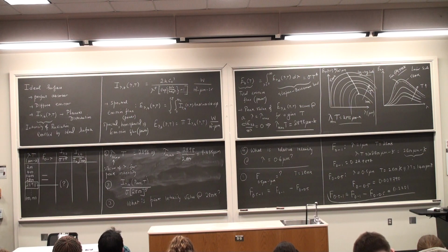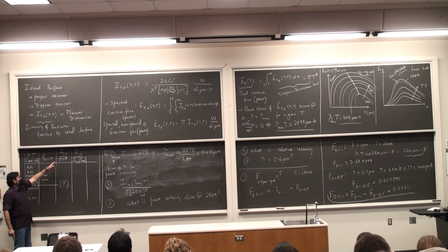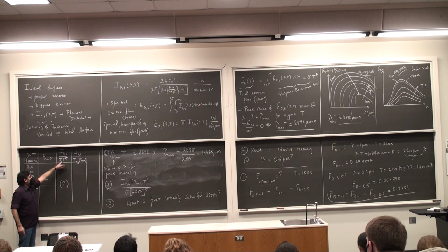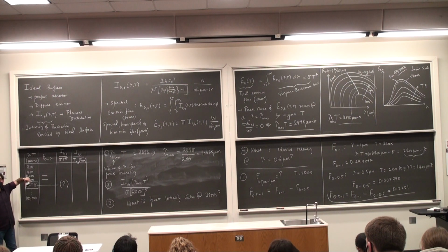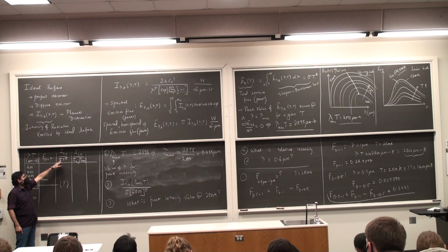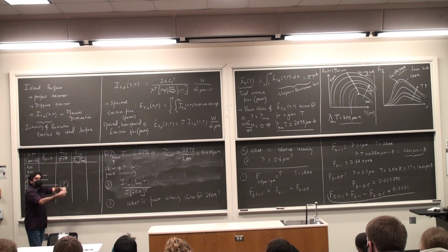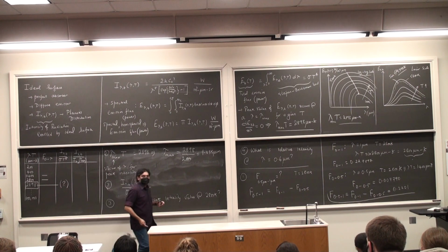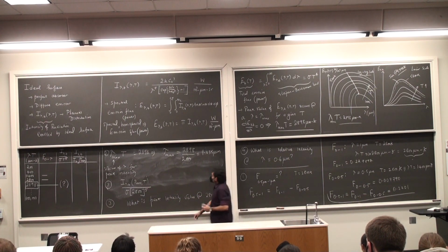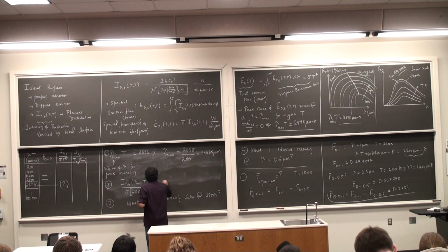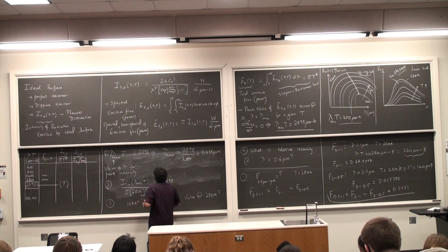So this is actually the fraction of the intensity per total emissive power of the ideal surface per unit temperature. That is, sigma T to the power 4 is the total emissive power. So this is I of lambda comma B divided by sigma T to the power 4, divided by temperature T. Okay, so per emissive power per temperature. It's just the way it is tabulated. And this is equal to 2898.